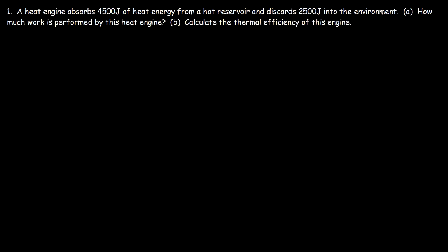So let's work on this problem. We have a heat engine that absorbs 4,500 joules of heat energy from a hot reservoir and discards 2,500 joules into the environment. How much work is performed by this heat engine? So let's draw an energy flow diagram.